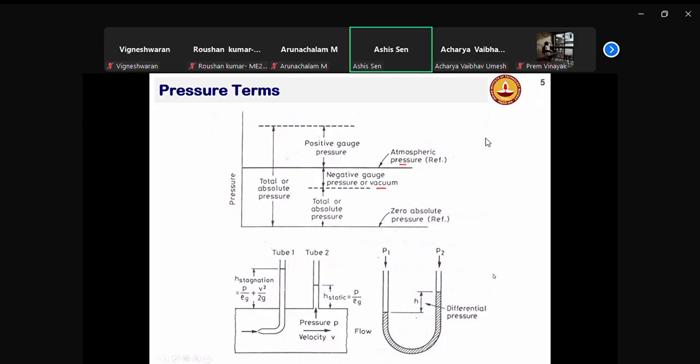So, as you said, what is important is the reference point. One way is that if you have a curved meniscus, both in the left limb and right limb, you take the center lowest point. Let's say you are using multiple fluids and something has some other meniscus.